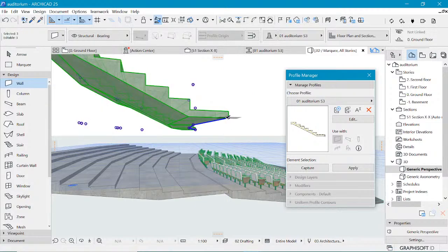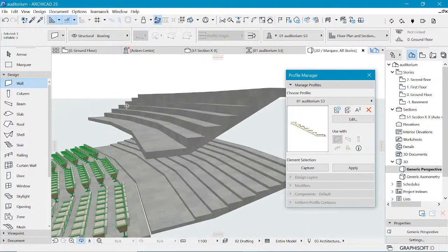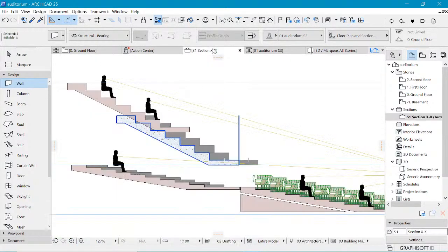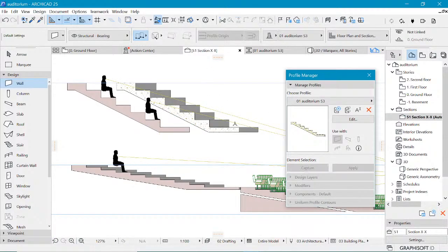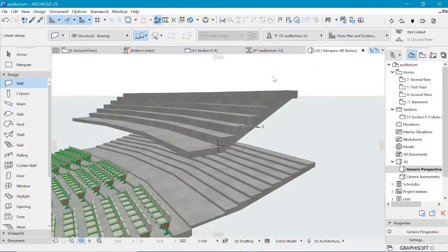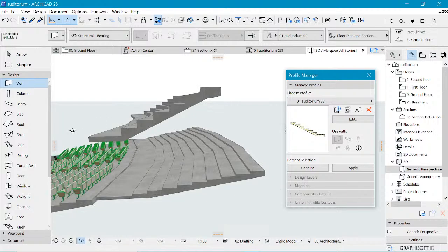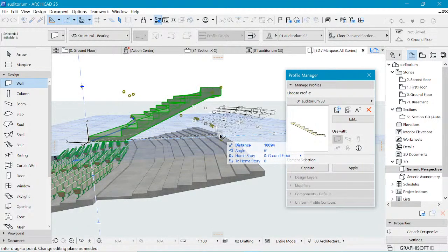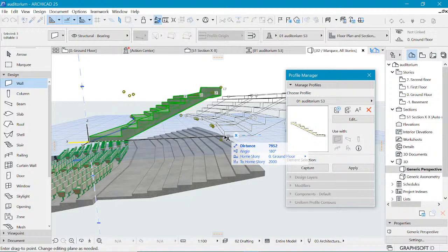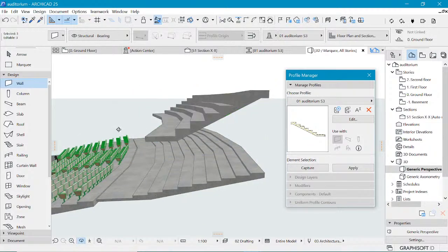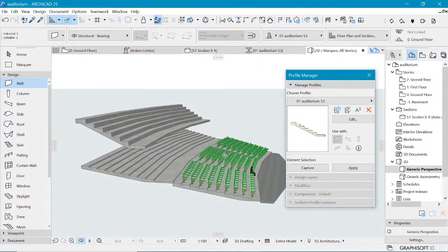So we have something going on here, which is pretty cool, but we need to also put it in the right place in the section, which is by moving backward by 3 meters. So we want to go back here, and you can use the vertical plane or even this other plane. Just move it backward in the x-axis, yeah, by 3 meters. I'm avoiding moving it in section because in section we cannot select all the 3 that I have just drawn. So it's better for me to move it around here such that now I can see where it's going. So that's it.